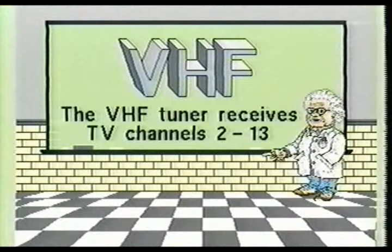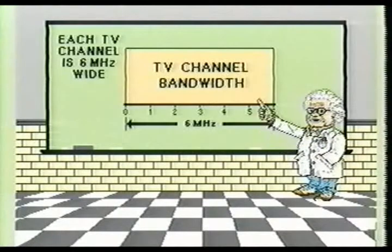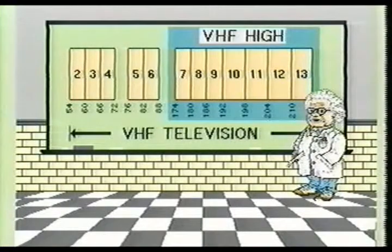The VHF tuner is designed to receive television channels 2 to 13. Each television channel has a bandwidth of 6 MHz. Television channels 2 through 6 are designated as being low-frequency VHF channels. Television channels 7 through 13 are designated as being high-frequency VHF channels.